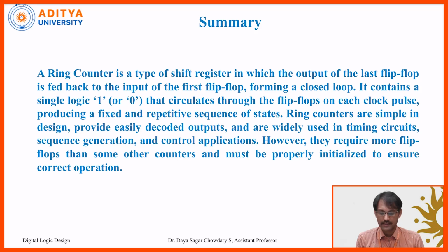Ring counters are simple in design, provide easily decoded outputs, and are widely used in timing circuits, sequence generation and control applications. However, they require more flip-flops than some other counters and must be properly initialized to ensure correct operation.